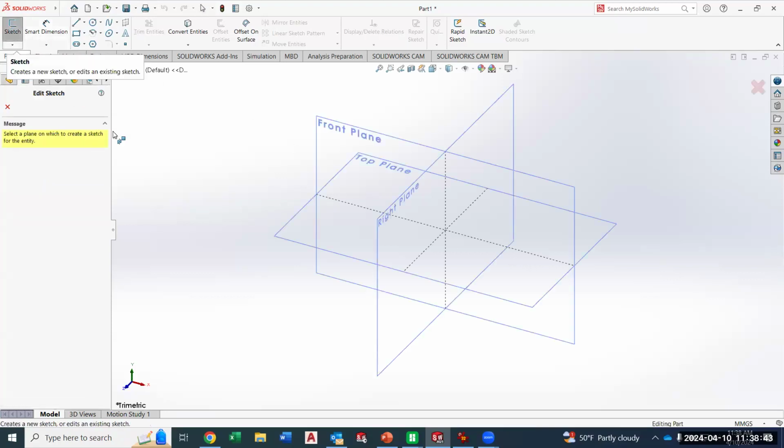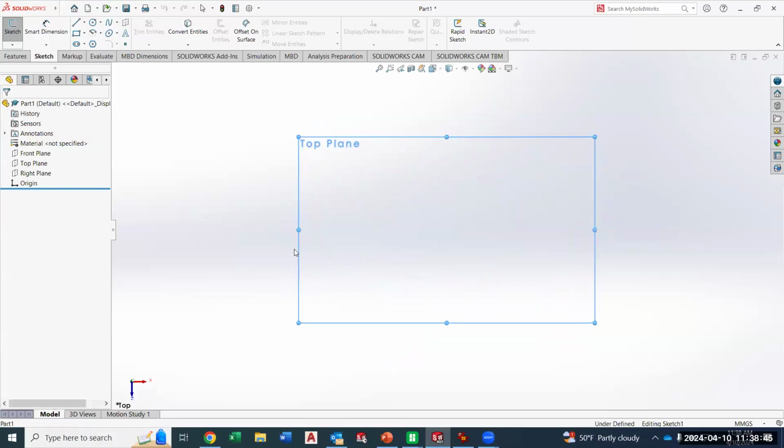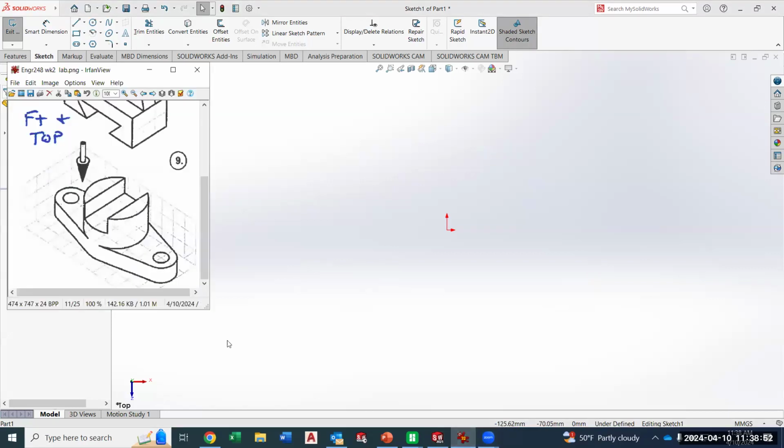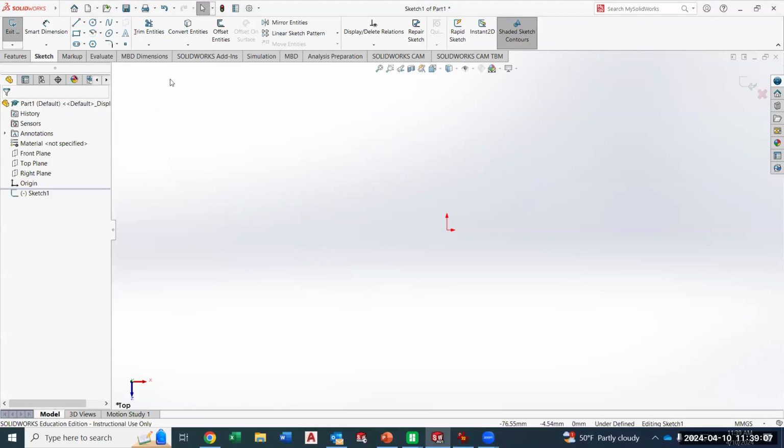And then I just go into sketching, and I'm going to show you how to sketch that bottom plane, some different strategies for that. What I want maybe is to locate, or at least give myself a line to work with to locate these two holes, and then I can continue to locate some more holes. So I probably would use a center line.